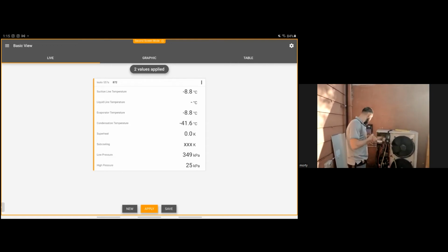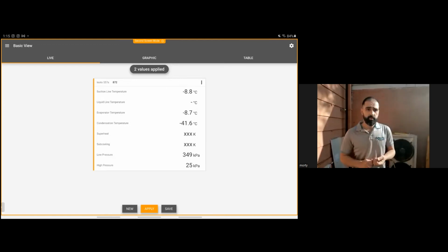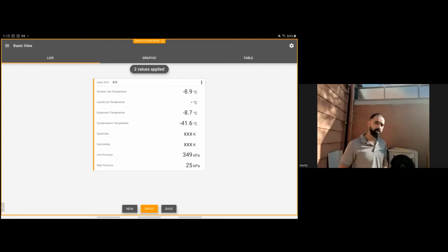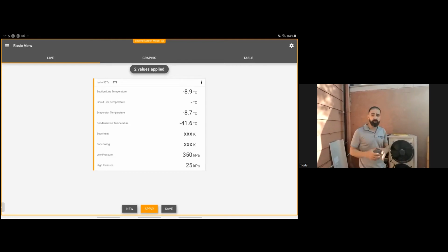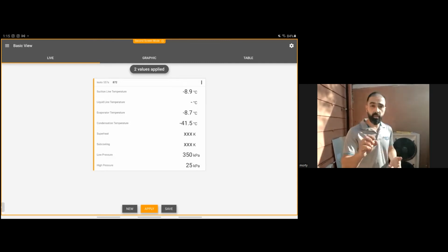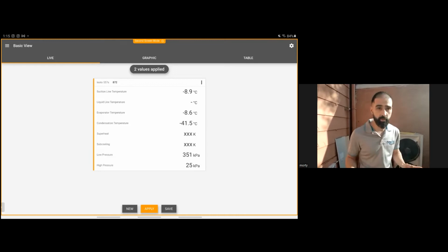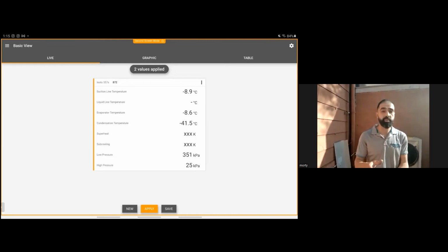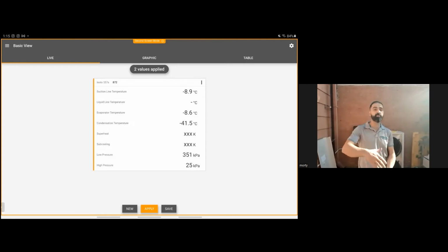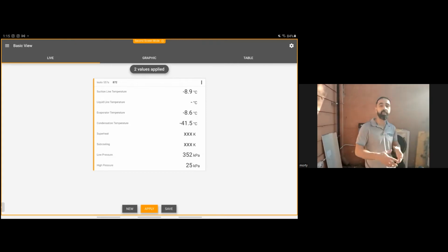What else are we able to cover up here? The sound of your compressor should always remain the same. If you hear a knock, or hissing, especially when it's off, say bye-bye to your compressor or your valve plate. Your valve plates are gone. If the compressor runs at normal temperatures and when it turns off, the temperature aggressively increases by double or more, then again, what happens in your discharge is it's seeping through to the suction and heating up the compressor. So I just hope I covered everything.